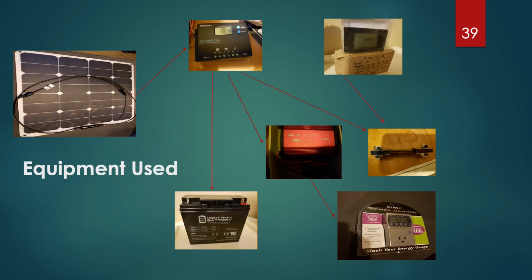Here is a collage of photos of the equipment we used in our mini model, which lines up with our circuit diagram. To start, we have the solar panels that convert sunlight into a DC current. That current flows to the solar charge controller that feeds power to our solar battery, our solar inverter, and our shunt. Once inverted, we measure our power through the power monitor on the bottom right. With that data, we are able to analyze how much power our system is absorbing and storing, and we can tell whether there is a fault in our system.